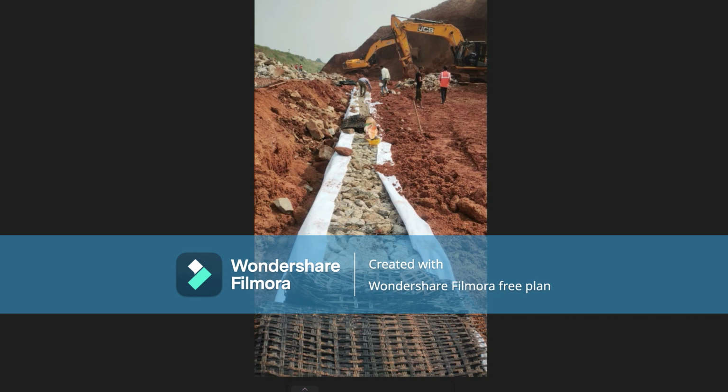So first, below, we can see in the drawing they provided the foundation and the gabion box with boulder gabion wall facing and boulder packing. The boulders are packed in the box with the geonet also provided. Every box is 2 meters long, 1 meter wide, and 3.5 meters high.